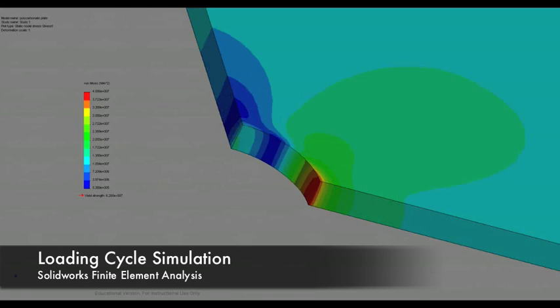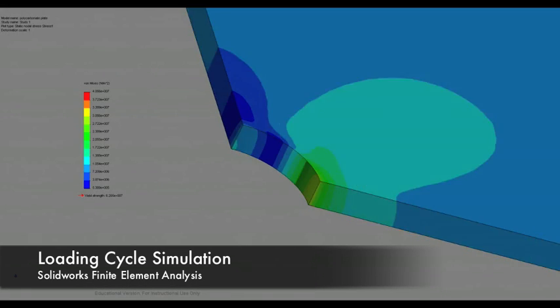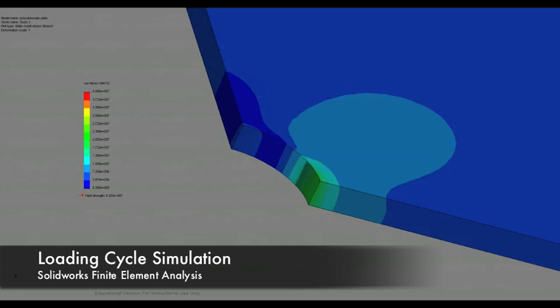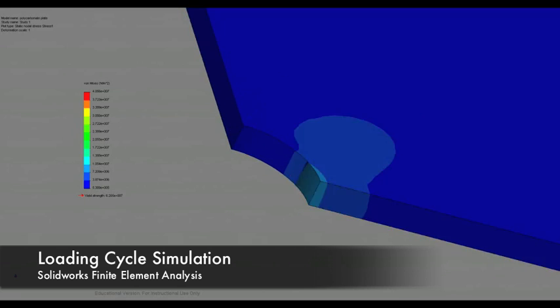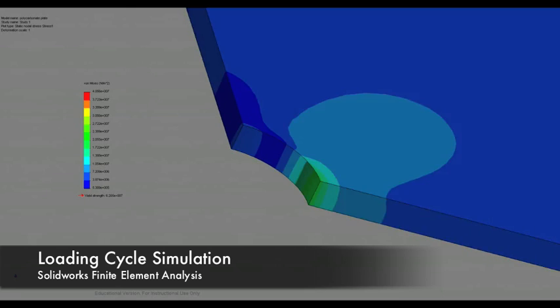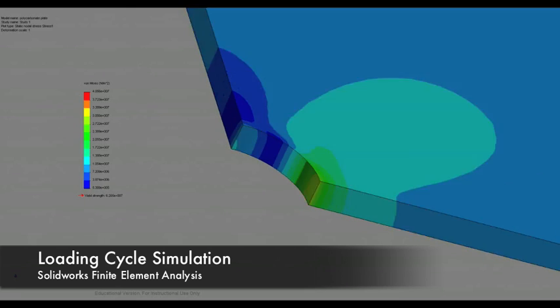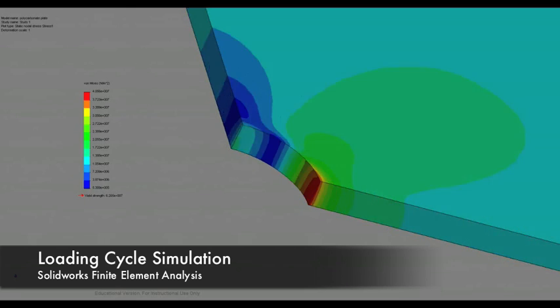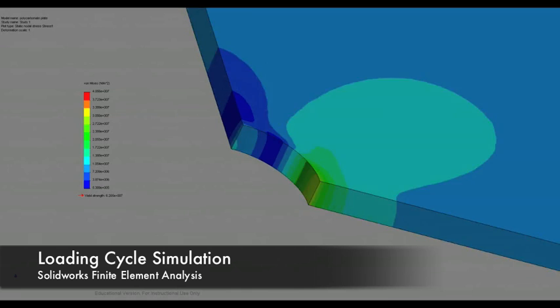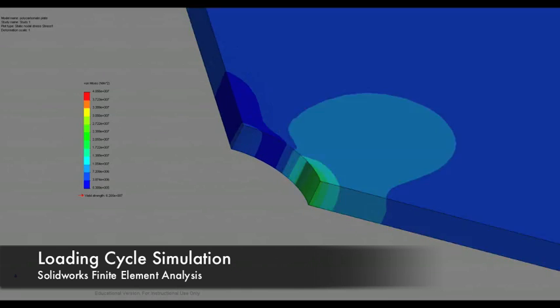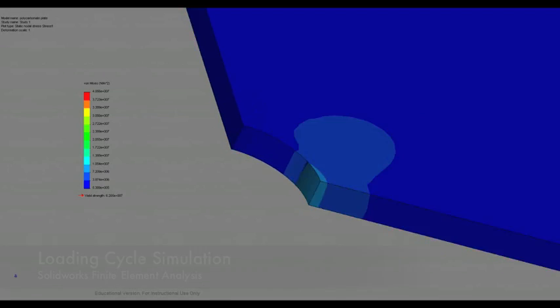This video shows a simulation of the uniaxial loading and unloading cycle that was later conducted using the Instron machine. Recall that blue corresponds to the minimum stress, which in this case corresponds to when the applied load is 0. So, when the entire plate is blue, there is no load applied on the plate. As load is applied, the stress concentration appears around the hole.